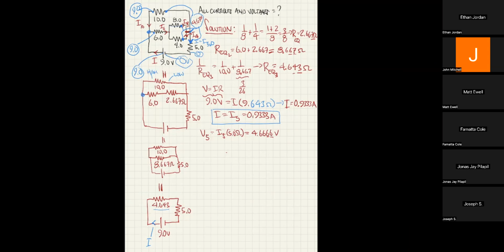But I will stay at that height of 9 volts until I get to the left-hand edge of the 6 ohm resistor and until I get to the edge of the 10 ohm resistor, again, the left edge of both of those. Does that make sense? So try to think of circuits that way. It will actually help you.